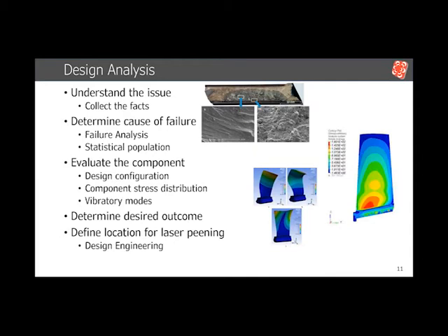Once you've begun to collect all of the data and understand the issue associated with it, it's now defining and understanding what you really want to get to. So you have to evaluate the component. In doing that, it's looking at things like the finite element model, and also understanding the vibratory modes, how that part works, so you understand the stress distribution in the part, and being able to model that part.